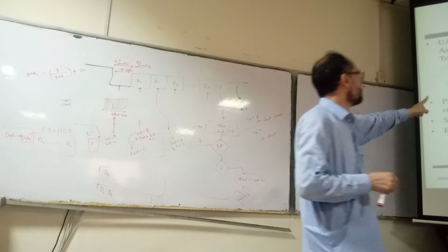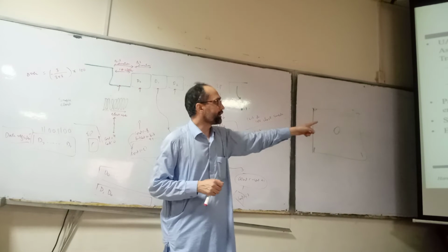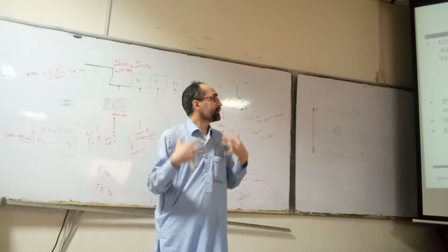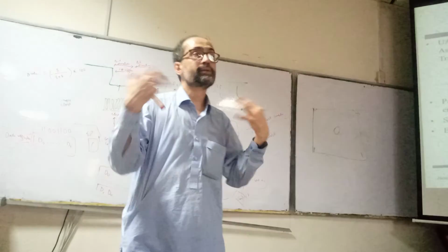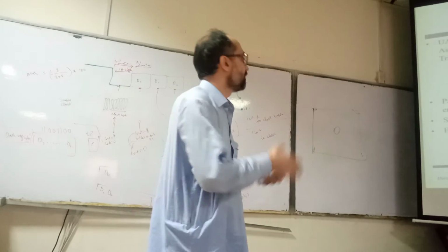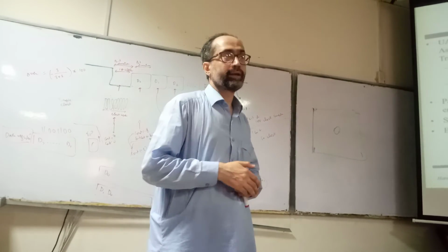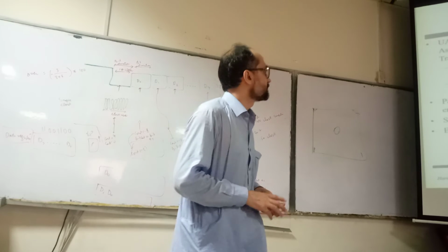So the parity bit is the extra bit for error checking. So we have the start bit and stop bit, and now the baud rate. The baud rate determines how the signal changes per second, whether it is changing fast or slow, and the bit rate is usually higher. So these are all the parameters of a UART.